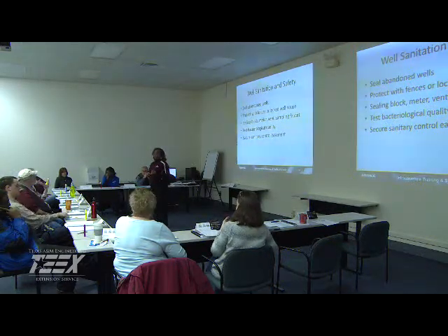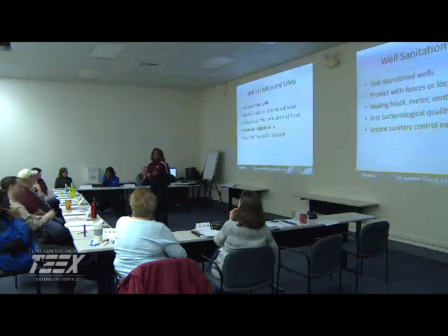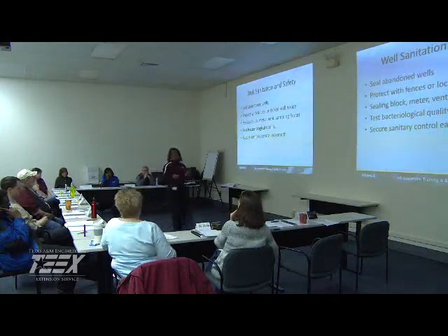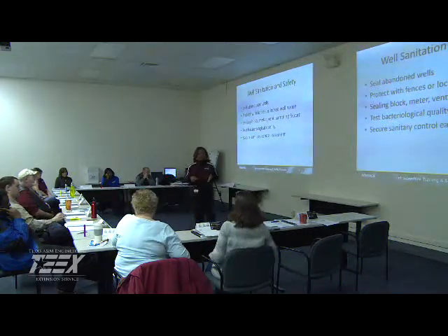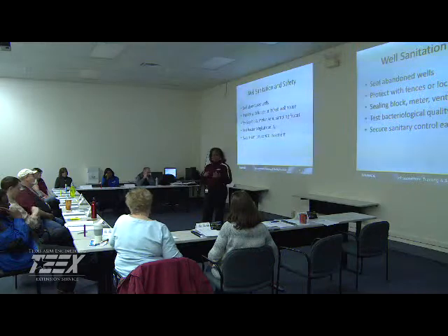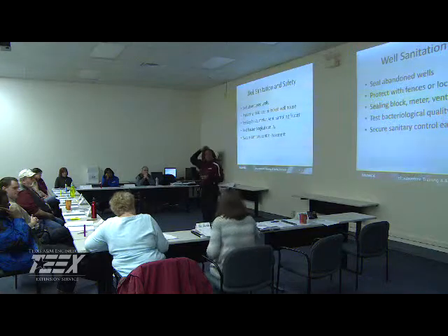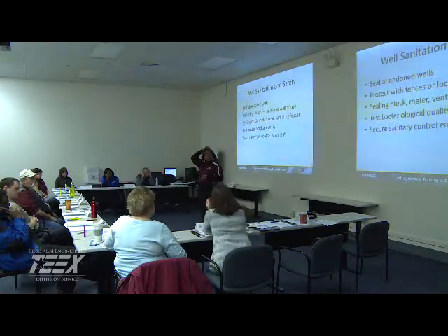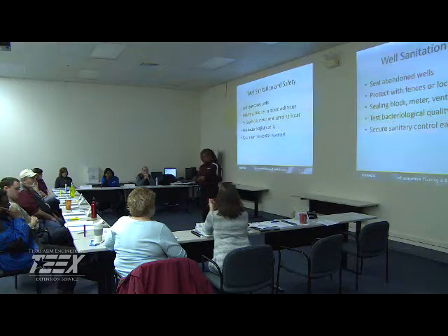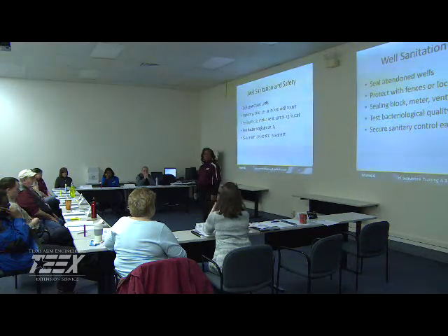We don't control the wells. With wells, it's a minimum of 6 hours after, depending on the dosage that you're putting in. You allow that to set for 6 hours, but it depends on what type of disinfection you're doing. Maryland requires 2 days, but what they do is let the well run for like 20 straight hours, and then they pull a 100 milliliter sample. So of course it's going to come up good. When you shut down and put it in normal operating conditions, then can you get a good sample? But all that running probably does help improve the water quality.